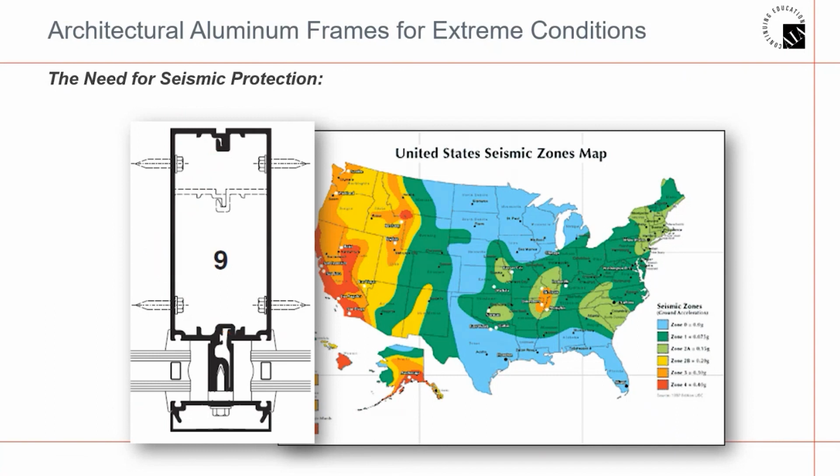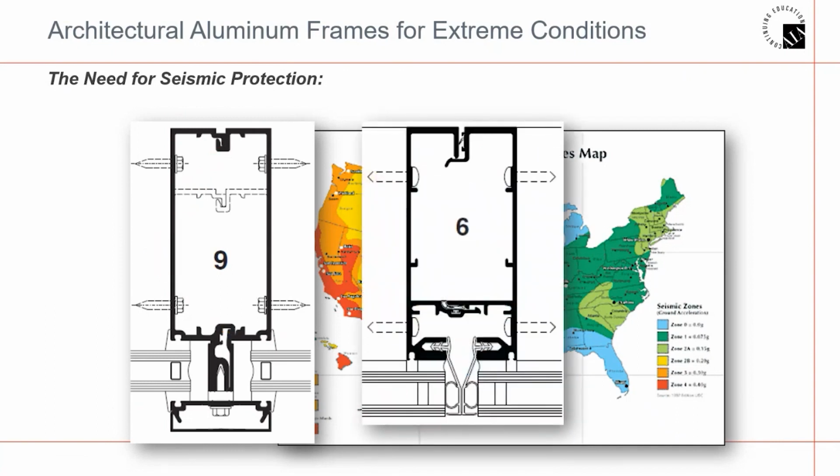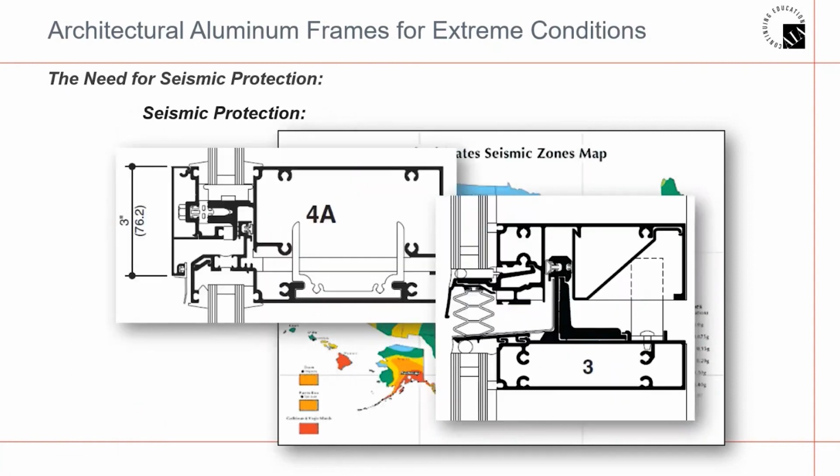And here's another example of a unitized curtain wall. Unitized curtain walls perform very well in seismic conditions because they're built in modules that allow slip and movement between them. This last detail shows you the horizontals stacked together. This type of stacking allows for movement to occur between them. The other half is hanging from the floor above and not load-bearing on the lower one. This is a unitized fabrication. It lends itself to very strong performance in seismic application.